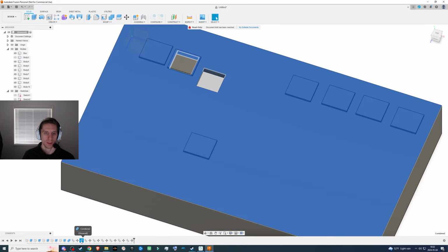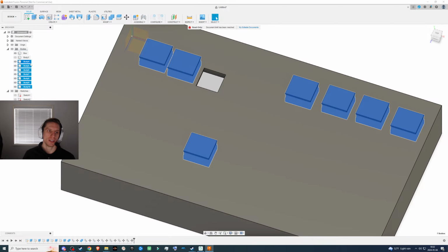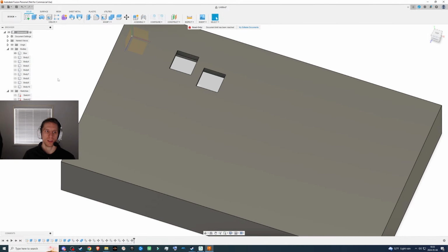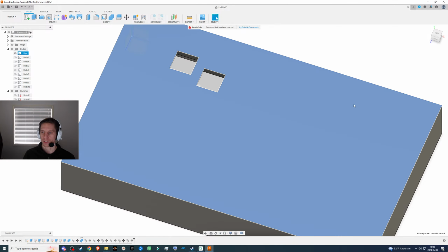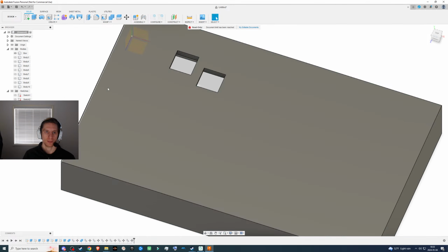So here's another thing we can do. First off, you can shift click all of these and you can hit V, and now they're all hidden. V is toggle visibility. I can also click on an object in the world and hit V. It's gone. V. Let's go ahead and put these in it.